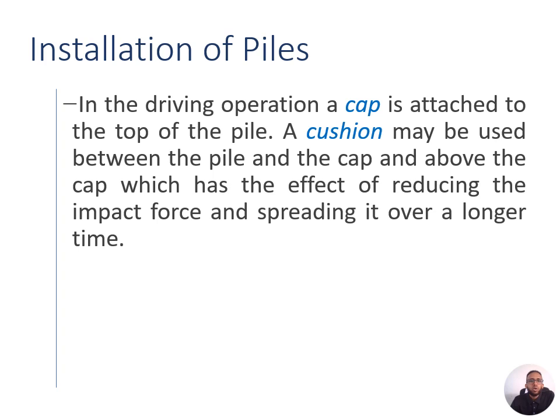In the pile driving operation, a cap is attached to the top of the pile, and a cushion may be placed between the pile and the cap. This cushion helps us reduce the impact force. It also spreads the force over a longer duration. This technique enhances the effectiveness of the driving operation, so that we can install our piles safely.